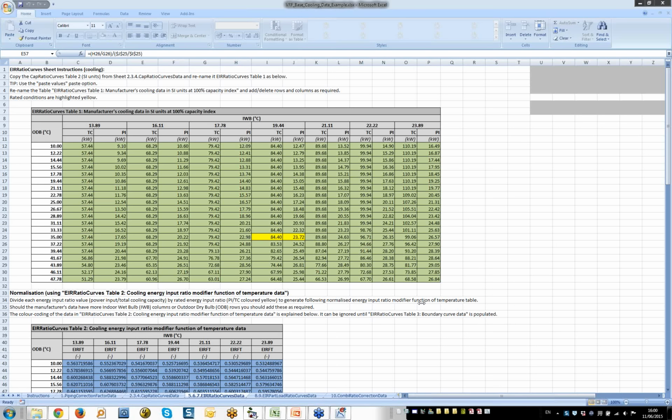What Autodesk have done is they've translated the Fortran version of EnergyPlus, that was EnergyPlus 8.1, into C++, and that's provided some great speed improvements, not in all cases. In fact, in some cases you do see even a small reduction in speed, but that's only in certain unusual situations. As far as we've seen, generally speaking, even for small models, you'll see around a 15% increase in speed.